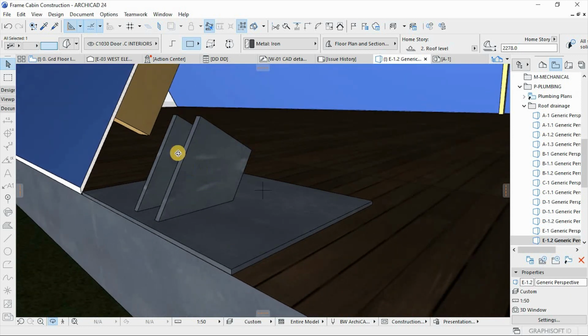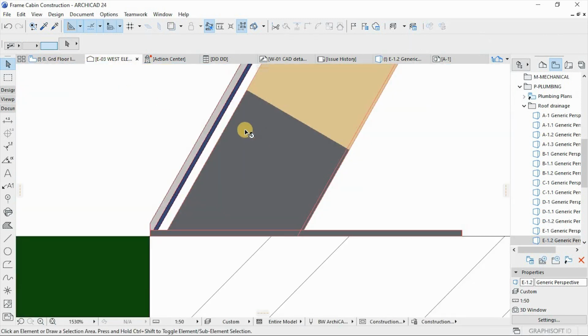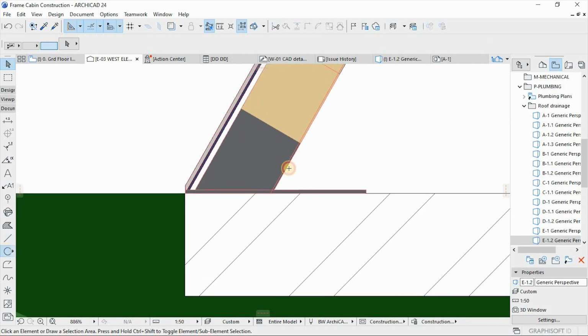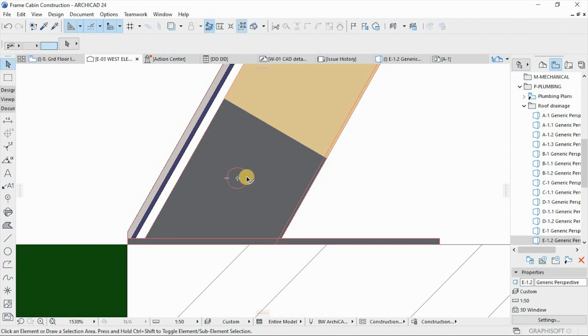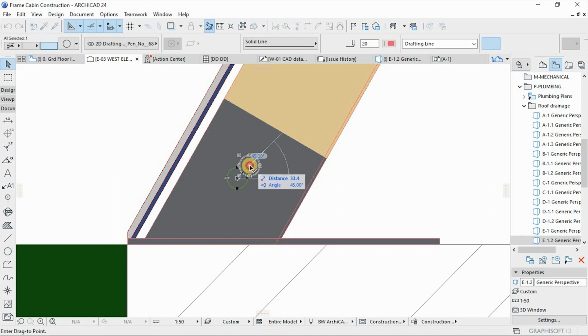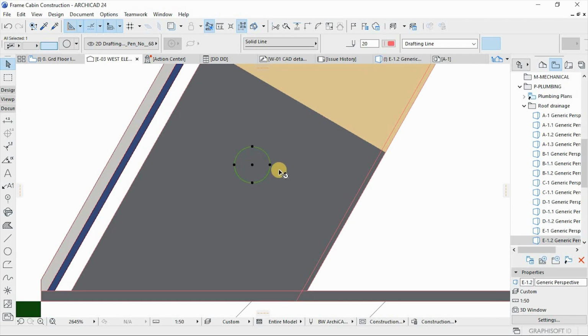So we have the bolts that will connect these two. I'll create the hole for that. Go to that section, then pick the circle, draw a circle of the hole. The diameter of the hole is going to be 20, so the radius is going to be 10. No, it's 20. Something like this. And then make sure you position it in a perfect position.